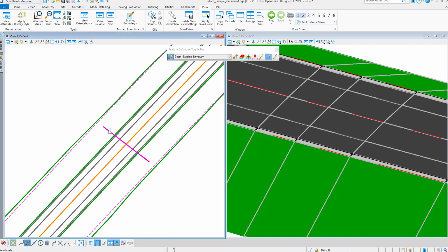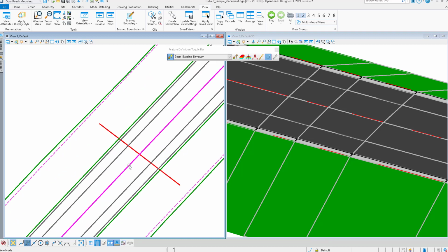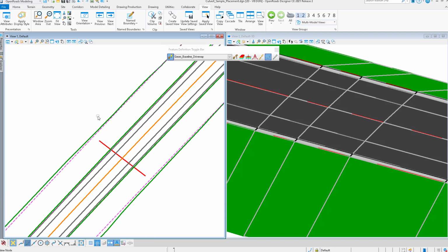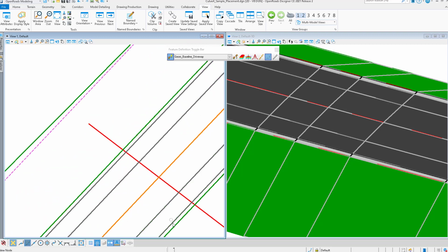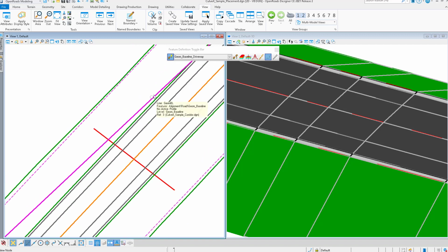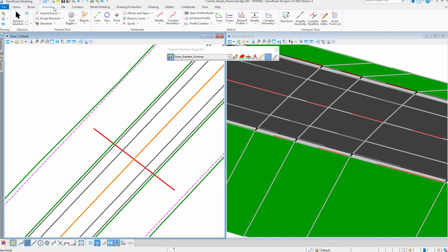So we have this first parameter for the civil cell. We need also the alignment of the road and the hinges for the slopes. But in fact, we need copies of them in the area of the civil cell. We don't need the whole corridor. In real life, the corridor may be really big, so we'll just duplicate the three elements we need in the few hundred meters next to the future culvert. And in order to do this, we'll just use a single offset partial, and we'll activate create 3D automatically.